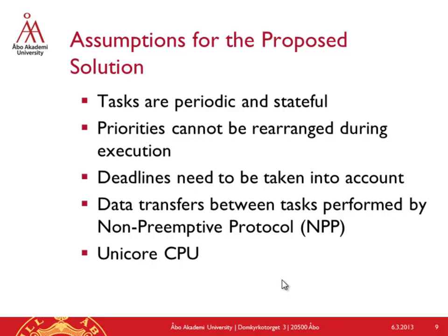But in the real world, these tasks contain so-called memory blocks, if you're defining them with Simulink. So they have their own internal memory. This means that the output data of this task will depend not only on this particular input, it will also depend on the previous states of this function or the previous input data as well.